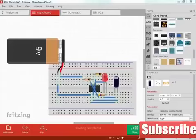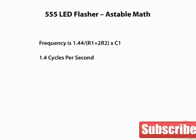There are lots of ways to make the connections. You'll get the hang of keeping things simple and neat with some practice. For our basic astable circuit, the frequency of the oscillations is given by the equation 1.44 divided by (R1 plus 2R2) times C1. We chose these values for our circuit so that the frequency of the flashing is about 1.4 cycles per second. Let's see what happens when we change the value of C1.